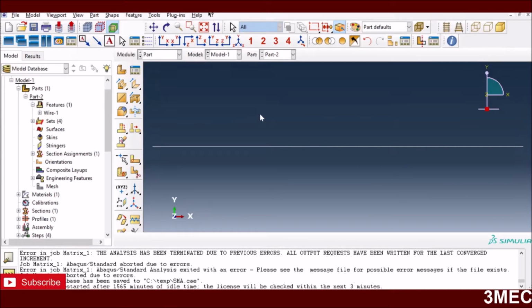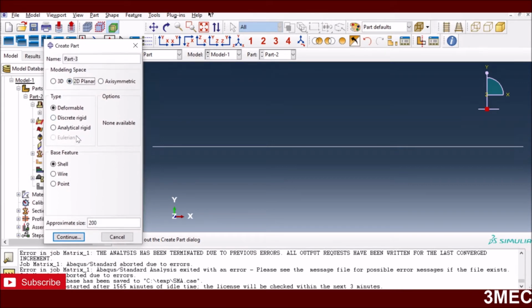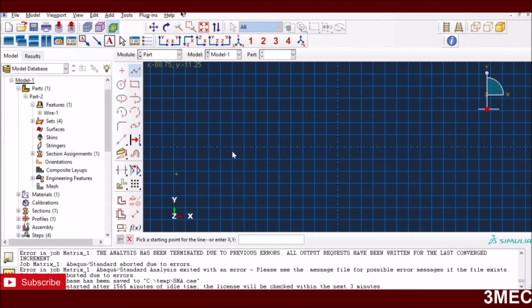Okay, let's jump into the details of how to model this. So I have already created a model. What I did was, to model the fiber, I have just created this single line. How you can do it is go to the create part option, select 2D deformable and then wire. Then you can select a cable.